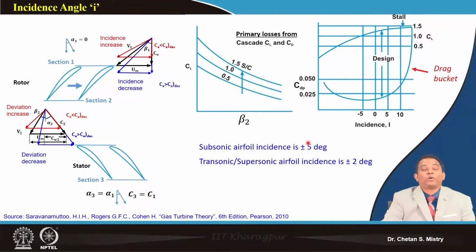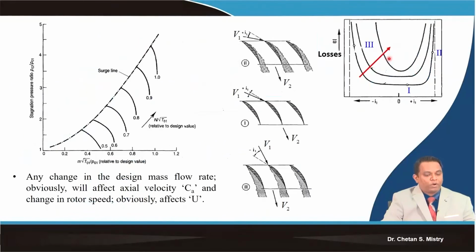Now when we are talking about the transonic aerofoils, my leading edge radius is smaller, and that is very sensitive. We intentionally look for a smaller leading edge radius because we want attachment of our shock with the blade, and that's the reason the leading edge radius is smaller. So that's the reason it is very sensitive to the change of incidence angle. Now here in this case, let's see what all the changes will be. Here this is representing CD and CL. Now what is our interest?